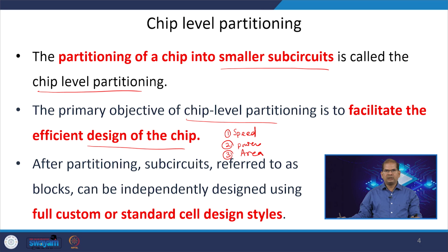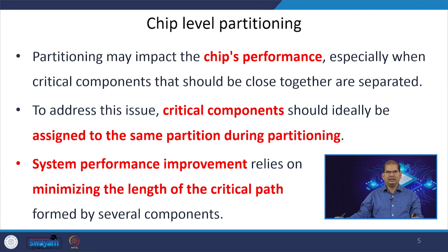We have different types of design styles. We have the full custom design style, and we have the standard cell based design style. Depending upon the different types of design style, we have different types of partitioning. Basically, different types of partitioning algorithms will be applicable for different types of design style.